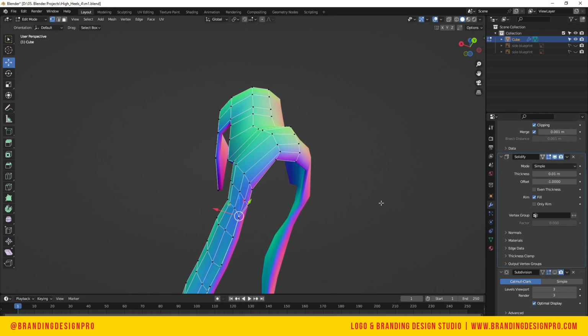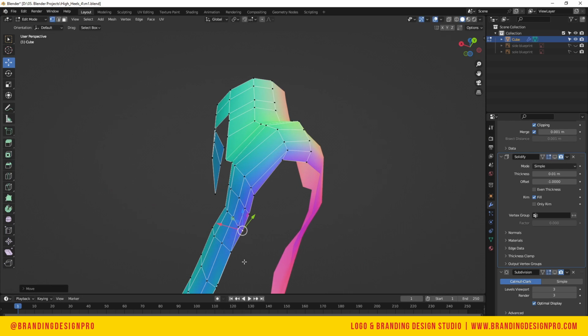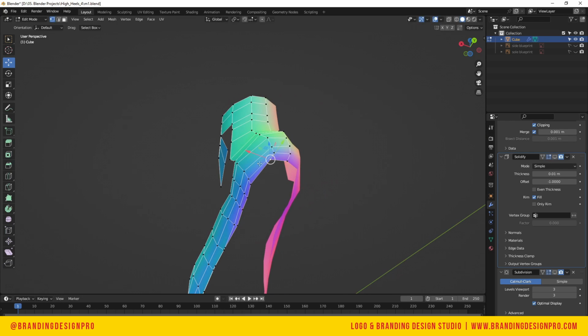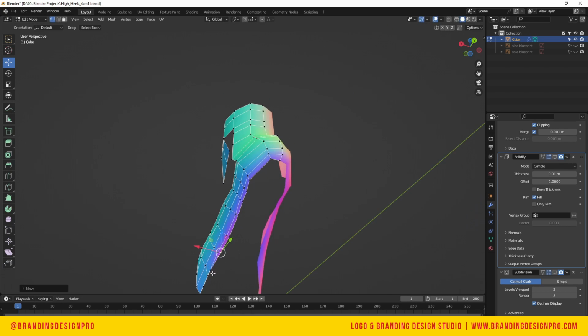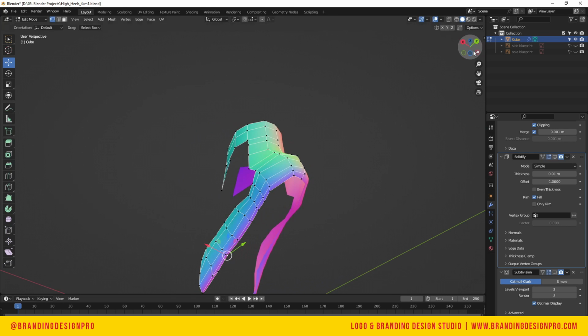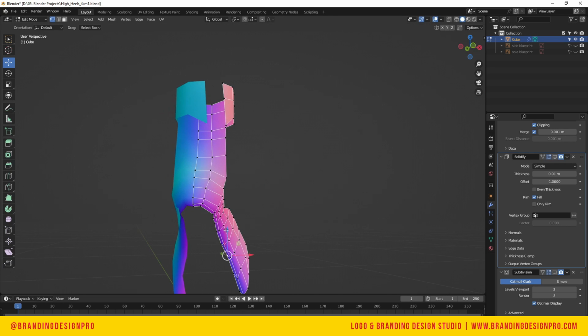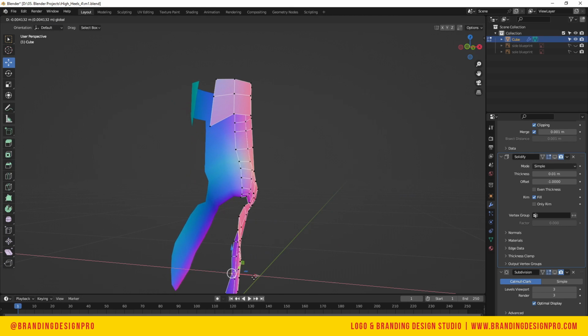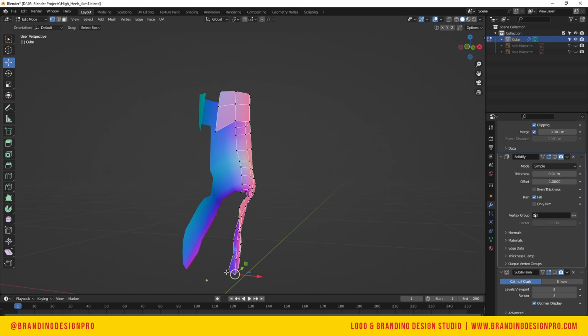You might have some overlap, so you might need to get in close. You can select the vertices, hit the period on your right keypad to get close to it with your camera, or scroll out to zoom out, and then just adjust that, bring them inward. Now, once you've done that, you're going to need to rotate it so we can adjust it some more. All right, and then just G, Z, bring them down. Bring that one in, this out, down.